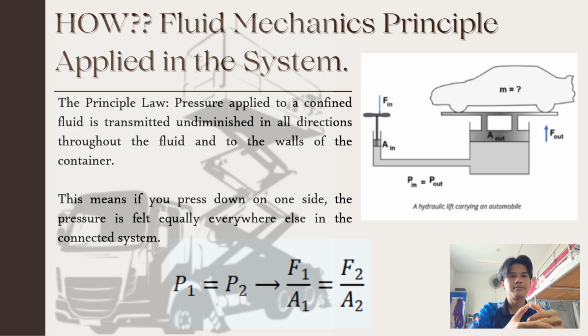The relationship can be shown by the equation F1/A1 = F2/A2. From this equation, we can see that increasing the piston area increases the output force. That is why hydraulic systems are widely used in car lifts, brakes, and heavy machinery.